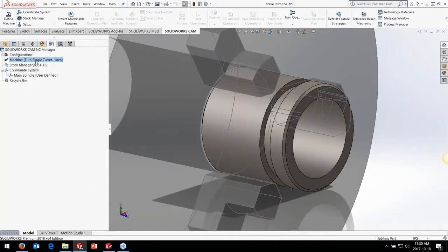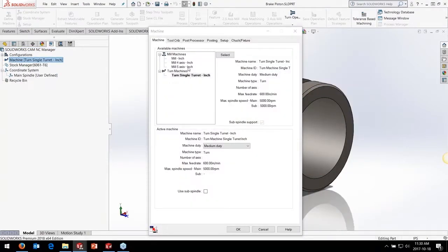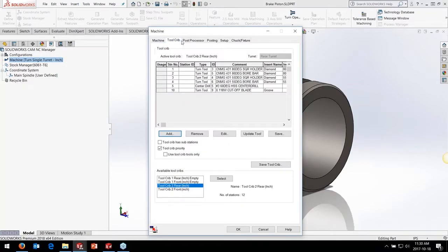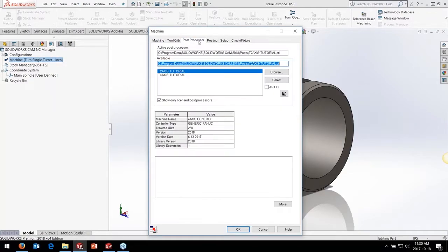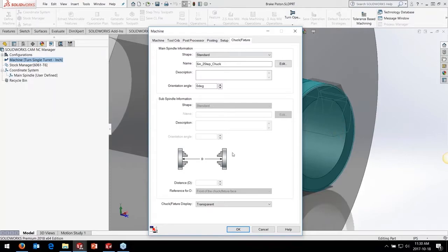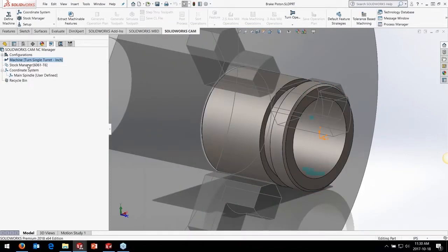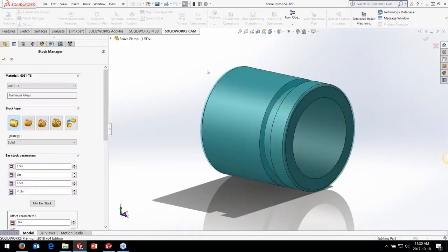Stock is obviously now cylindrical. Most of the time you're putting cylindrical stock into a lathe, but you can put in other types of geometry, other shapes, and other fixtures. If you want a fixture on the chuck to go and bore something, you can put fixtures on the chuck there as well. The feature recognition works the same sort of way, but in this case we're finding lathe features: facing, OD, groove, ID features, cutoff features, and things like that.